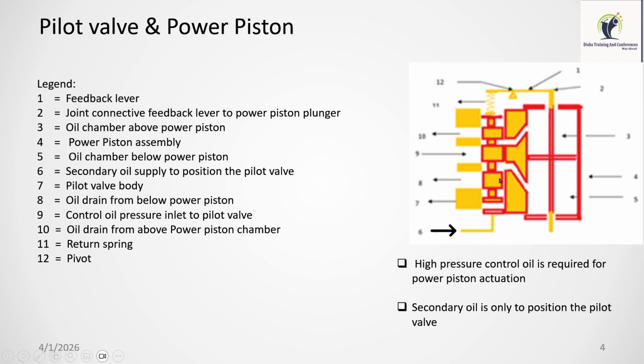This bottom will connect it to the drain, and due to high pressure it will come down. When this comes down, due to this fulcrum, this will go up and again bring the pilot piston to the center position. So no oil will go to the top and the bottom, and the servo motor will take its new position. This is the principle. This way the servo motor is working.